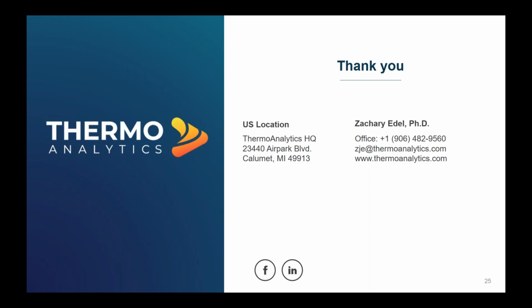How are you modeling the geometry of the jelly roll and core? So in this case, we have a shell part for the battery cell. The jelly roll is explicitly modeled inside the battery and connected to the case with thermal links. That jelly roll is comprised of shell elements that have multiple layers throughout them, so it has several nodes through the thickness of the elements. And then we have anisotropic conduction in that cell to account for the difference in conduction through the layers of the jelly roll and along the faces of the electrodes.